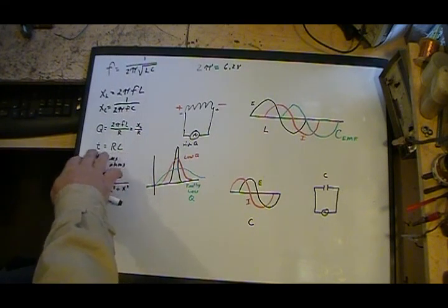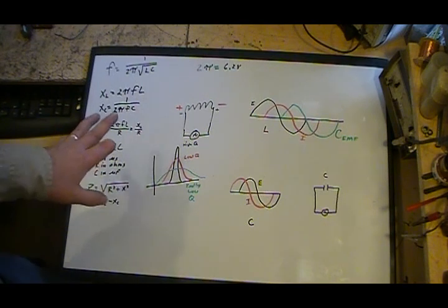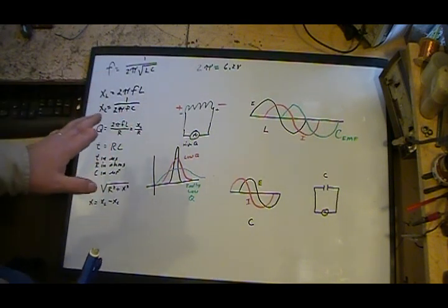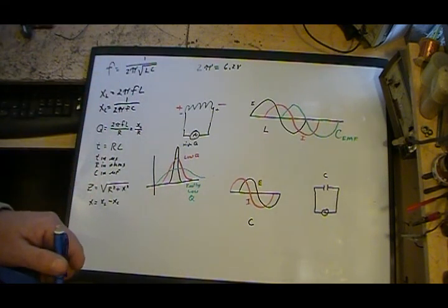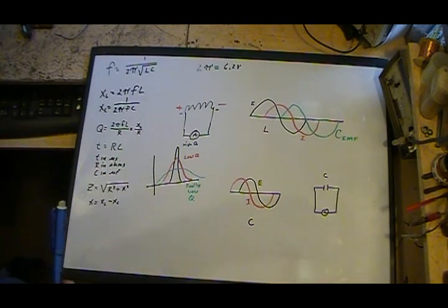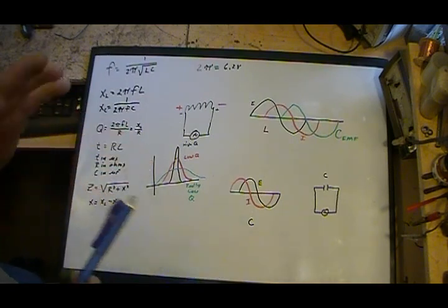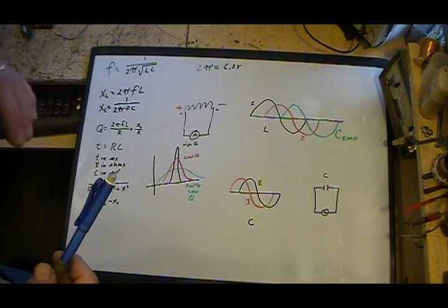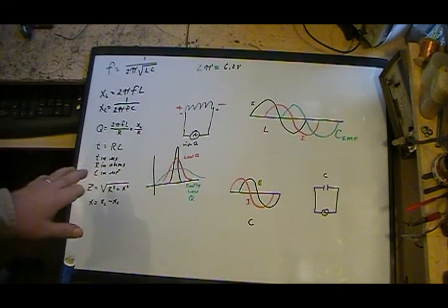So it's important to pay attention, especially, well, any area in the radio is important, but one of the areas is your AVC circuit, automatic volume control circuit. There's a time constant RC filter in there, generally around a 2 megohm resistor with a 0.05 as a general size capacitor.